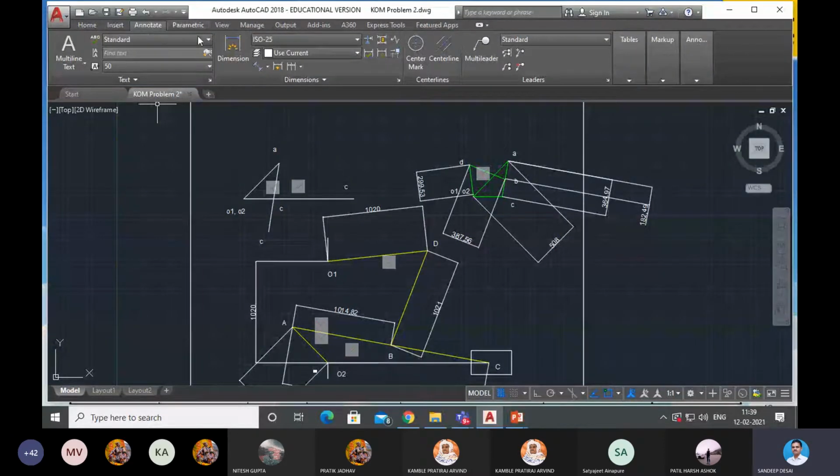And then this is not required. Shall I delete it? Shall I delete this? Now you got point C as a result of the intersection of AC drawn perpendicular to this AC and O1C drawn perpendicular to this slider path. It is nothing but O1C. Slider C is moving with respect to O1 or O2, so it is CO2 or CO1.